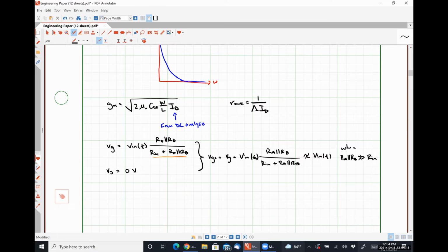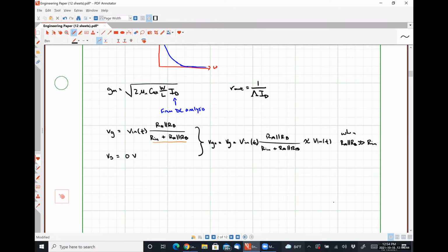That's typically not an issue because the internal resistance of our input sources is usually on the order of micro ohms, and we typically bias these with kilo ohm size resistors. But we could be trying to amplify a signal that has some associated large internal resistance that we would need to compensate for. So I just wanted to bring it to your attention.